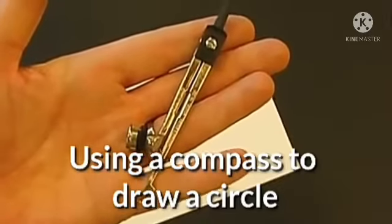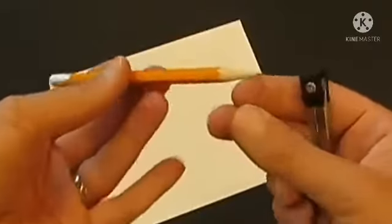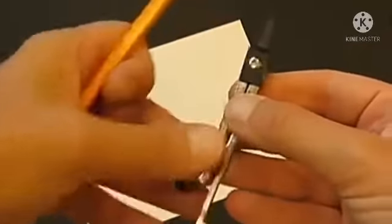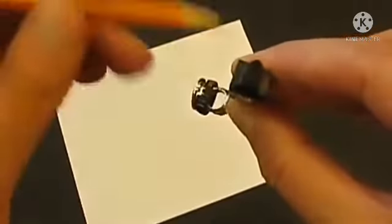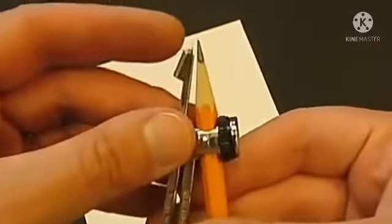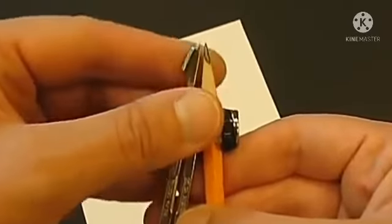Then using a compass to draw a circle. This is also a woodwork tool which can also be used on paper. So we have a demonstration on paper on how to use a pair of compasses. You put the pencil into the hole beside the compass. You loosen the nut, then you put in the pencil. You balance the pencil with the tip of the compass. Make sure they are on the same level.